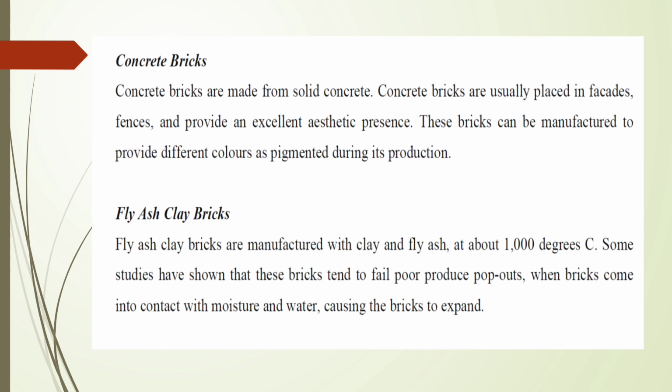Fly ash clay bricks. Fly ash clay bricks are manufactured with clay and fly ash at about 1000 degrees Celsius. Some studies have shown that these bricks tend to produce pop-outs when bricks come into contact with moisture and water, causing the bricks to expand.